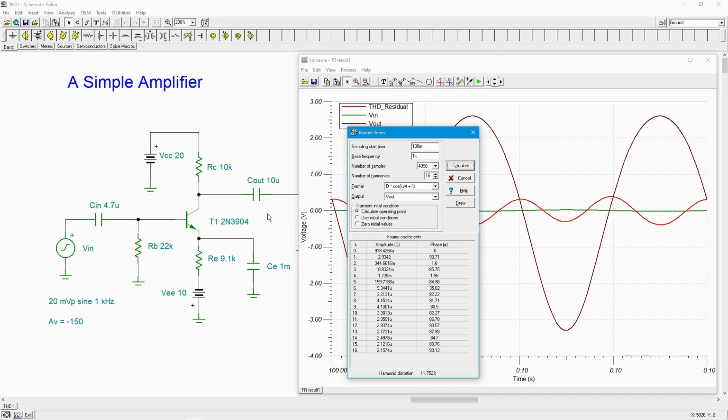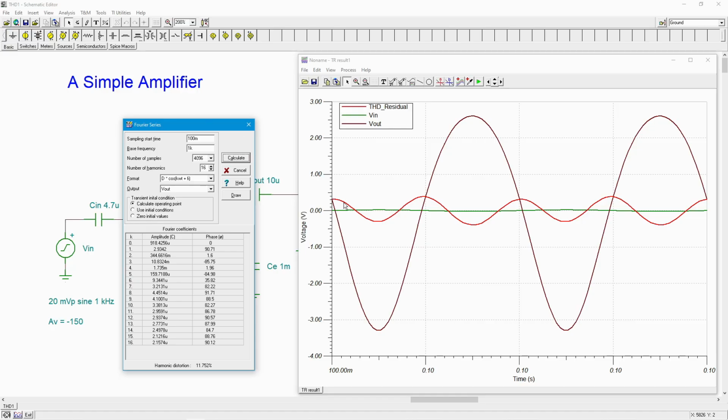So when we were looking at the plot there with all the little spikes, that's your input frequency. So that's coming in at just shy of 3 volts. It does show a phase of 90 degrees, but again, that's because it's a cosine waveform. So the cosine is 90 out, and then there's another 90 here. There's your 180, right? Because it is an inverted waveform. Okay. The next largest thing, number 2, is at 300 and just about 45 millivolts. That happens to be in phase. And that's what we see.